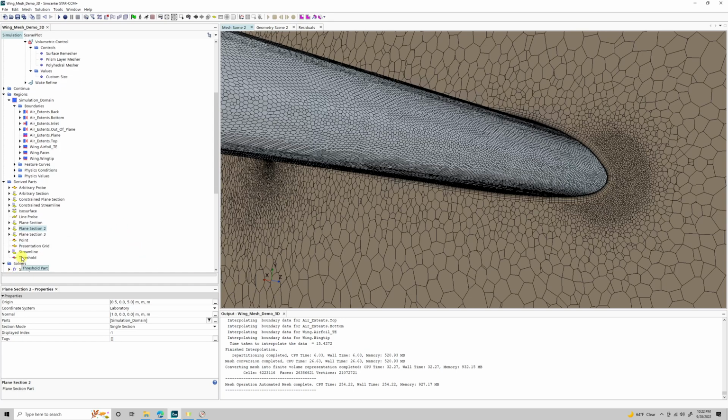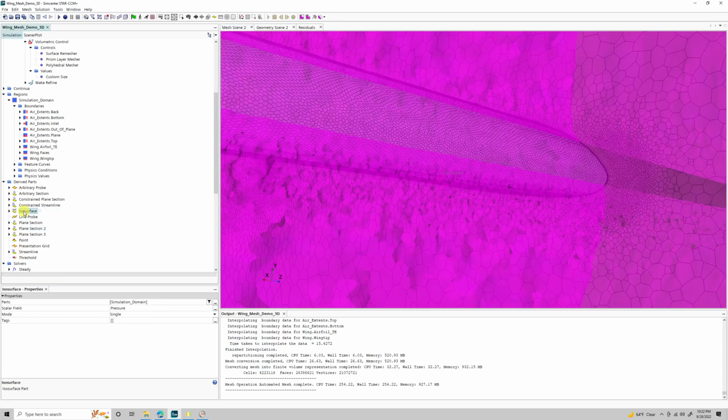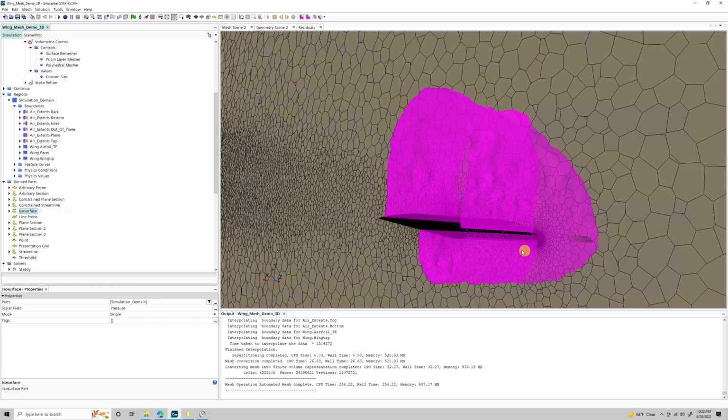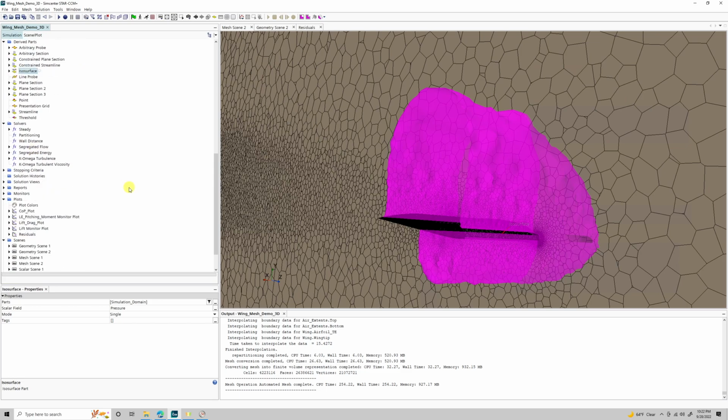Thresholds, very useful for debugging and visualizing regions of higher or lower values. Iso surfaces, also fun to deal with, and can be very useful depending on what you're doing. We talked a little bit about how to debug, specifically using thresholds and reports to find where there might be a problem, or that you know there's a problem, how to find it.